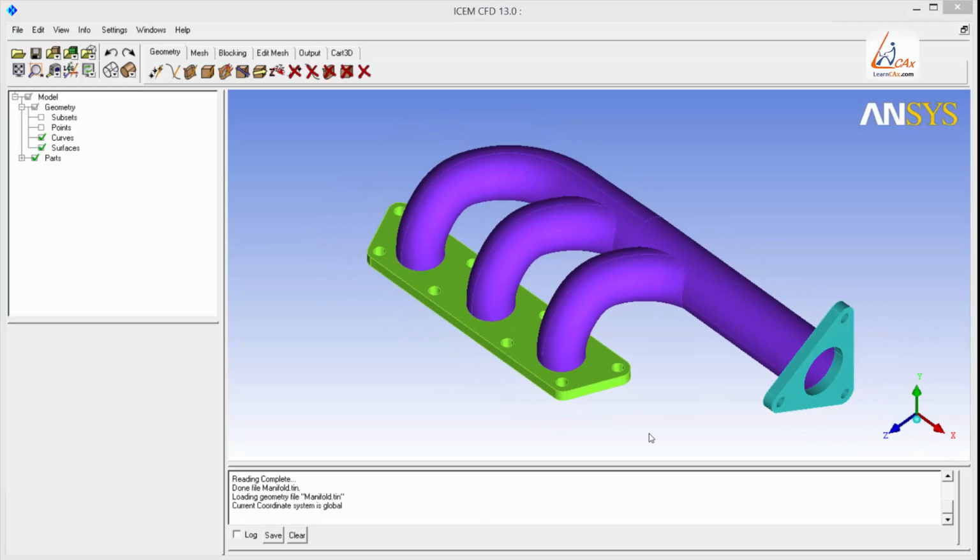This imported CAD model is a perfect solid model, and it has more geometric details than what is required for a fluid flow analysis. What we need for a CFD analysis, fluid flow analysis in particular, are the surfaces that are in direct contact with the working fluid. Those are nothing but the inner surfaces of the solid model. They are often referred to as wet surfaces in CFD terminology. We need to separate these inner surfaces from the outer surface. It will be difficult to select the inner surface while keeping the outer solid surfaces visible. So we need to select the outer surfaces, separate them into a different part, and then work on the inner surface.